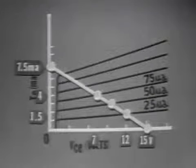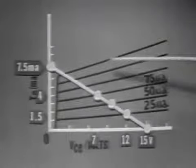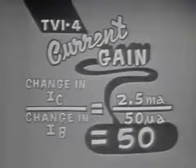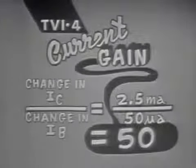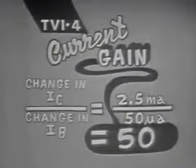From the graph, we have indications that a base current change of 50 microamps, peak to peak, causes a collector current change from 1.5 milliamps to 4 milliamps, or a total current change of 2.5 milliamps peak to peak. Well, with a 50 microamp change in the input and a 2.5 milliamp change in the output, what's the current gain? All we have to do is divide the change in the input current into the change in the output current. The current gain is 50.